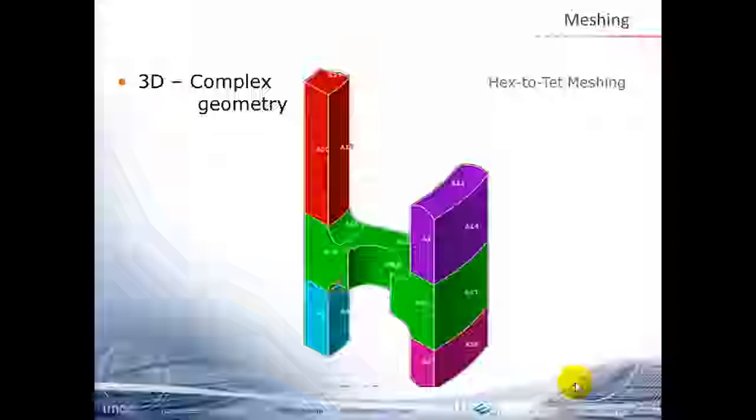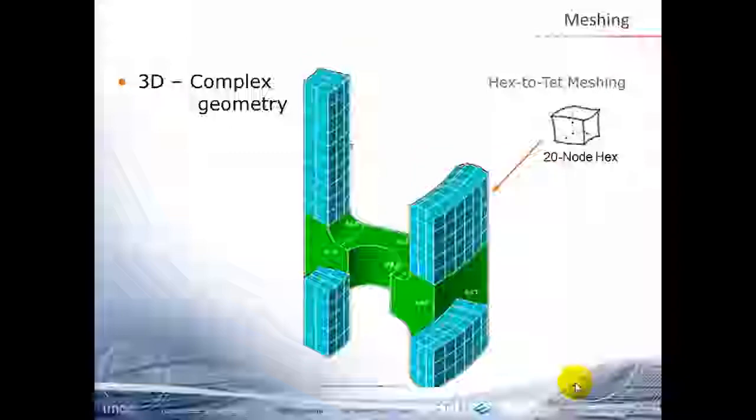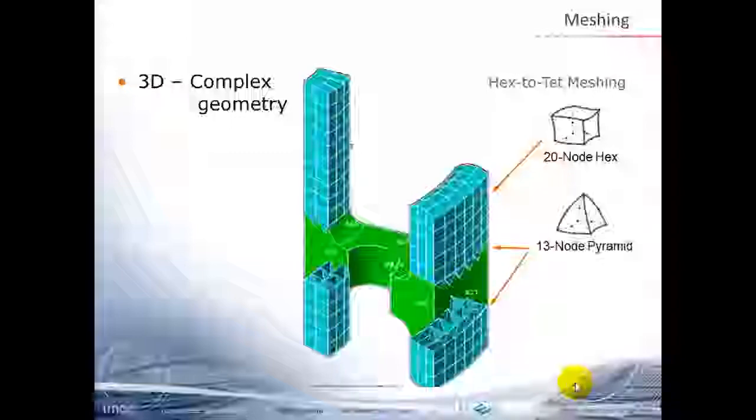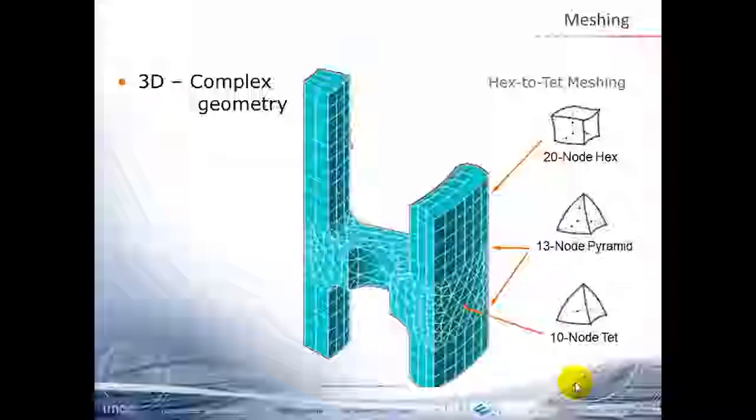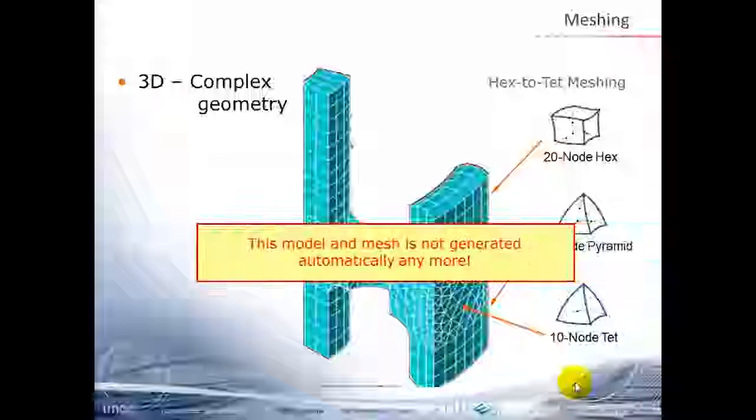And in this case, I have, let's say, separated the easy part of this volume, which I could mesh with very regular, let's say, 6-faced blocks. And I needed a kind of pyramid to interface the square area with the triangular area of the tetrahedra. And with the tetrahedra you can mathematically mesh any irregular shape. But again, this is done automatically.